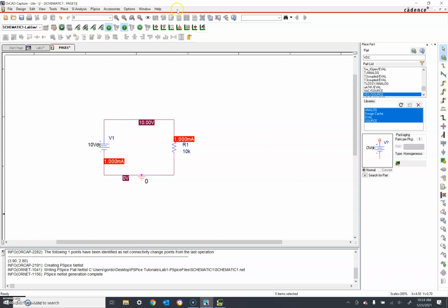Okay, we can also click the W, power. Okay, 10 milliwatts. I squared R, V squared divided by R, you get your power calculations. So we end up with 10 milliwatts here. Now notice we've got a negative sign on the voltage source. When it comes to power, negative 10 milliwatts. We got a plus 10 milliwatts here. What does that indicate? In PSpice, a positive power value indicates power is absorbed, and a negative power value indicates power is being supplied.